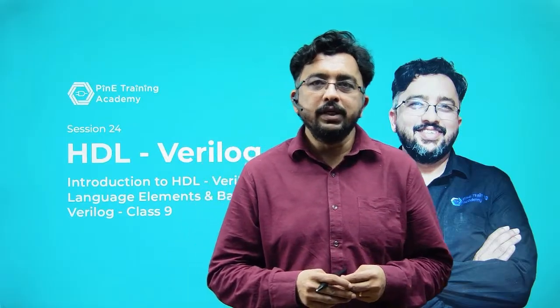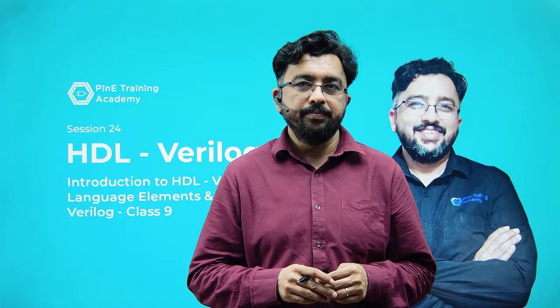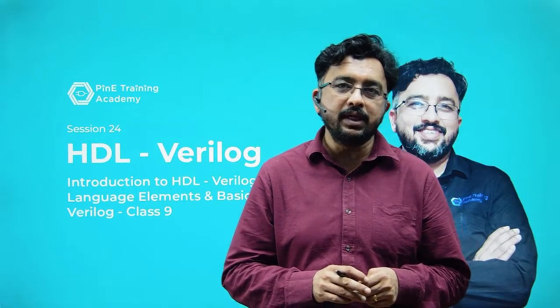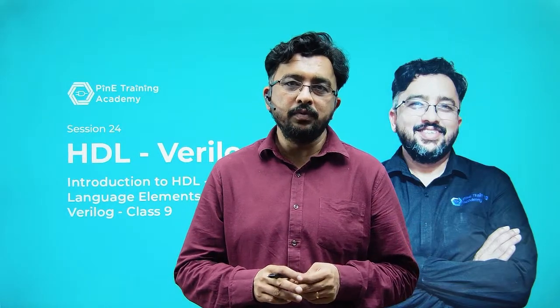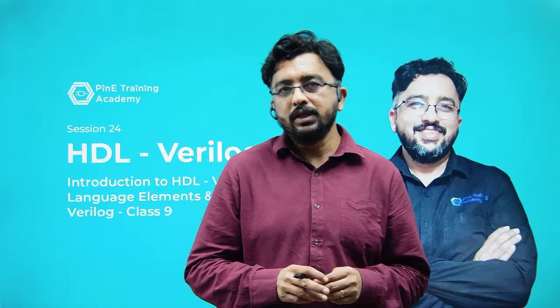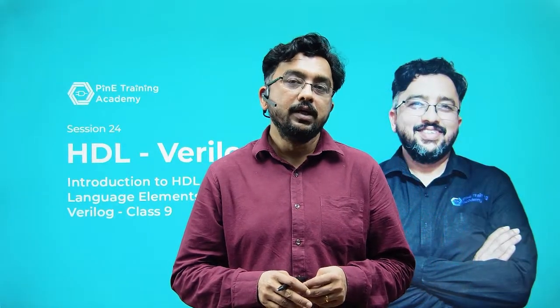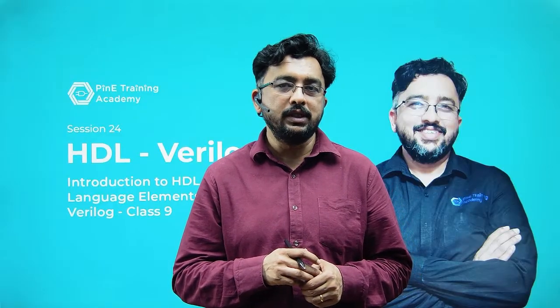Today, as I mentioned earlier, I'm working to give you the best basics of everything. We are currently working on the basic language elements used in Verilog. We started with data types: the connectivity data types and storage data types. We have finished the connectivity types, starting with wire and tri. We have not covered tri0, tri1, supply0, supply1, because these are part of the more advanced Verilog modules. We are focusing more on the storage data types.